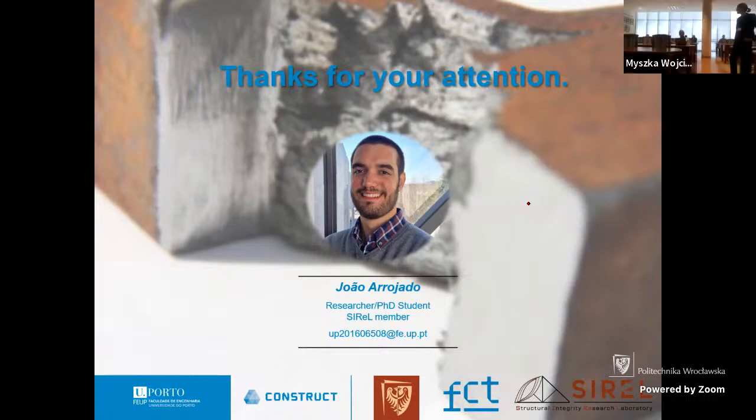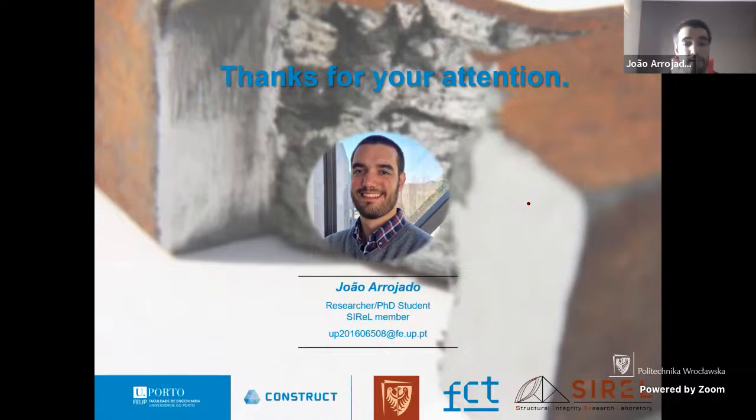Okay, and do you have in mind any post-processing of the additive manufactured part? Because generally the fatigue strength of the additive manufactured material in the as-built condition is not so good. So have you in mind some post-treatment? Yes, maybe. As I said, this is just a preliminary work.